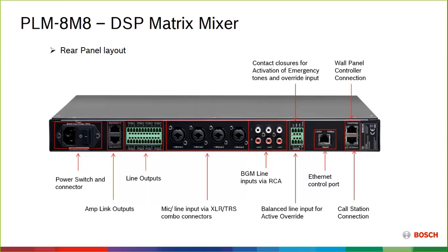We gave you those regular Euro block line outputs, and then also, of course, TRS and XLR combo jacks for inputs, and then what we call RCA connectors for BGM inserts. And on the right Euro block, you have in two tones. In some countries, you could use this as an evacuation system. It depends on your local fire codes. We don't see it used in the US very much as a true life safety system, but it does have the ability to play some emergency evacuation tones.